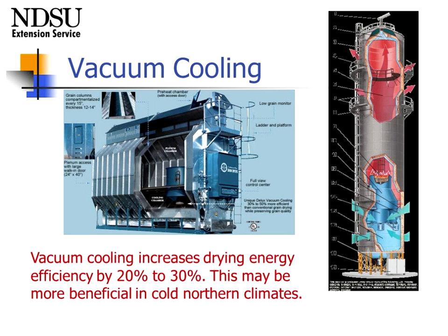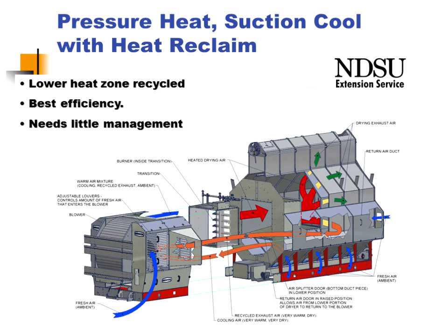Whether we put the fan inside the dryer as this one shows, or if we have it exterior as we've been showing previously. So a huge benefit, particularly I think for those of us that might be in the northern part of the Corn Belt, that as we're looking at cool outside temperatures, being able to capture that heat rather than just exhaust it to the outdoors makes a big difference.